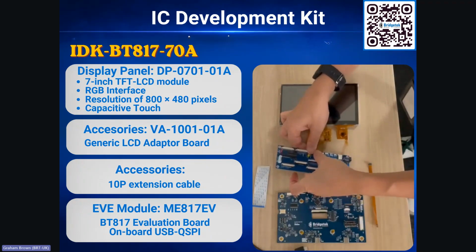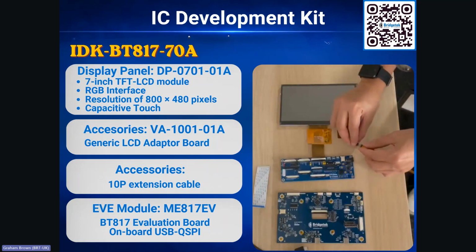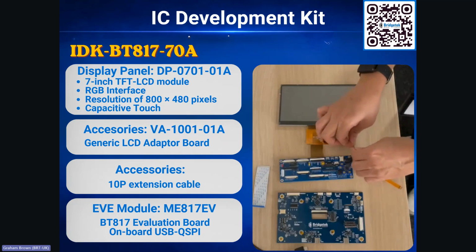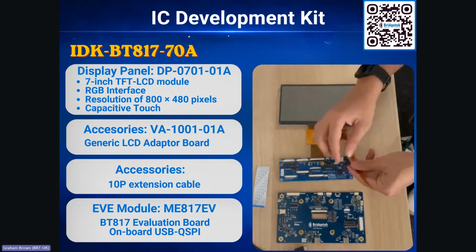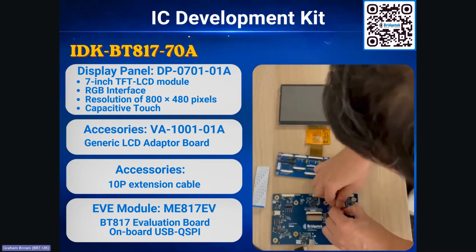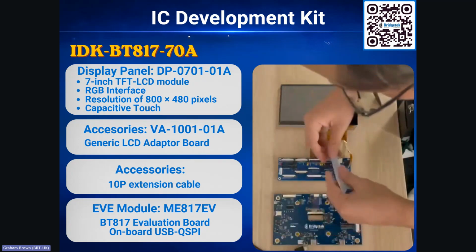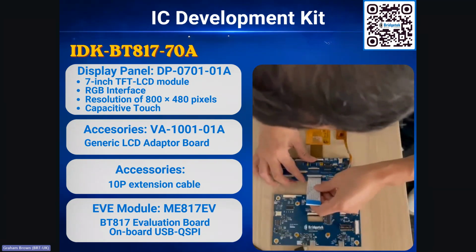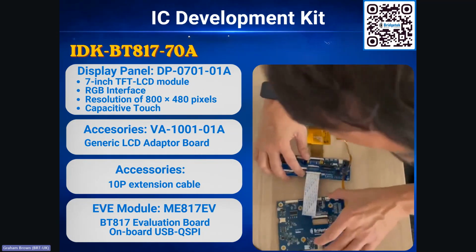It is paired with a bright 7-inch TFT LCD that features a capacitive touch, giving you the kind of responsive, modern interaction that users expect today. Here we are connecting the 10-pin touch extension cable from the display touch panel to the ME817EV. We have included the generic LCD adapter board and cables which interface the display to the ME817EV.